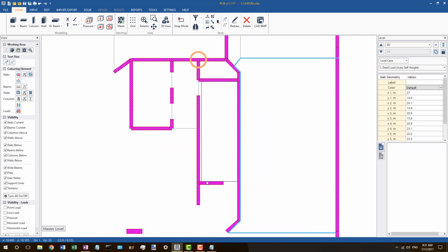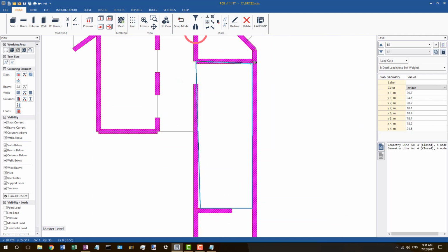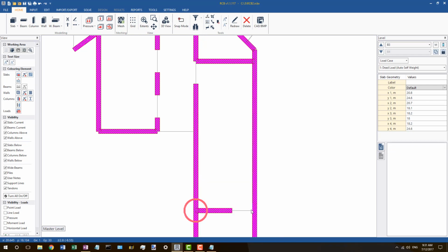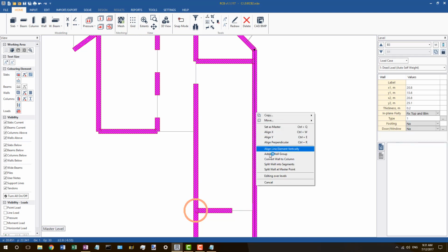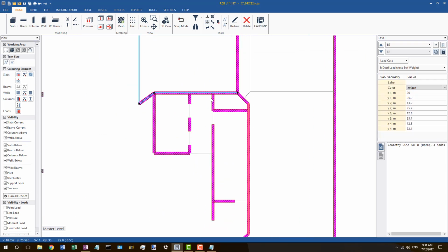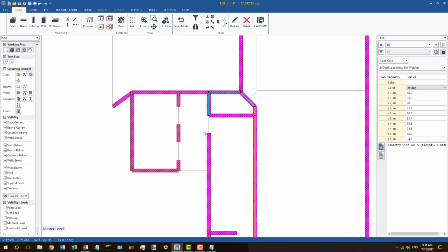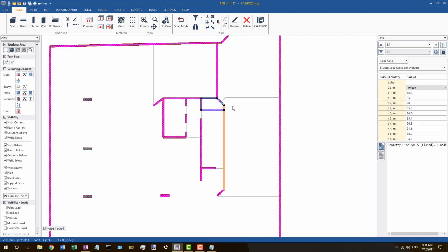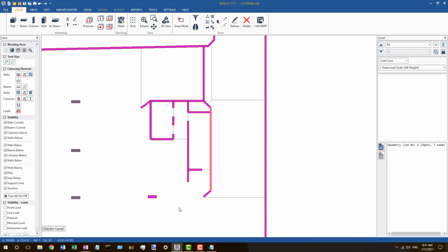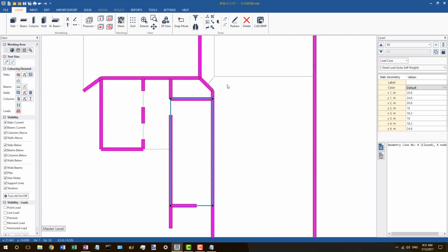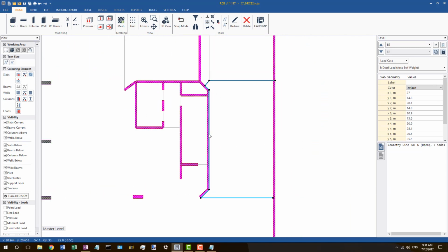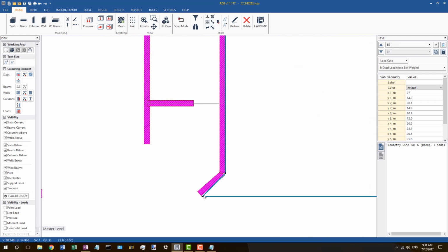And the stair shaft, snap to the center lines. So now this is all nice and neat. In this area, geometry lines are all snapped to the center lines of the walls, which is good. Next, we'll fix up this area where there will most likely be a car park ramp, or there is a ramp here. So it's come in as basically one solid piece. We have to model the discontinuity in this slab, which we'll do manually.